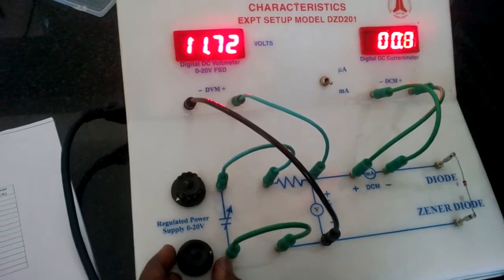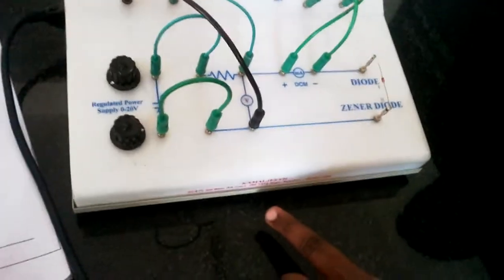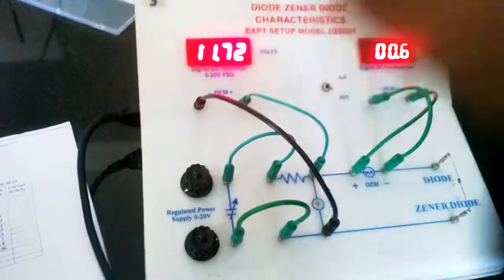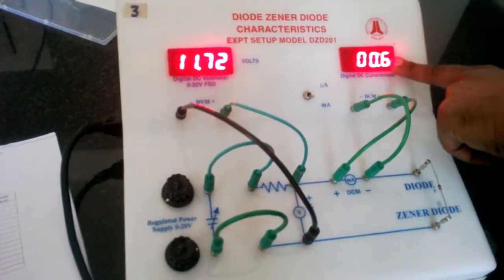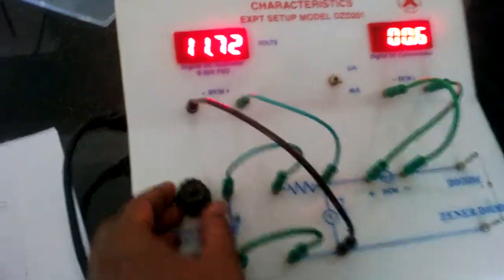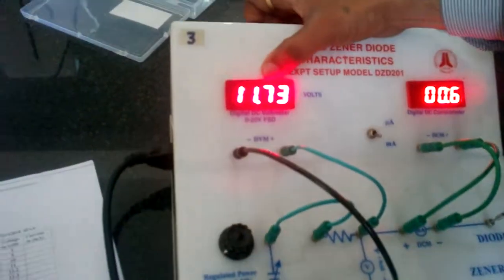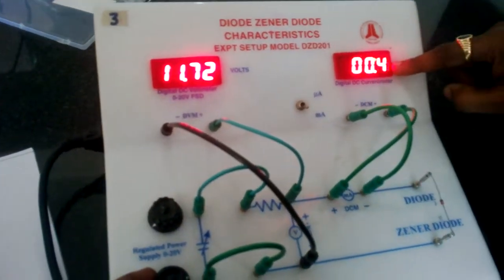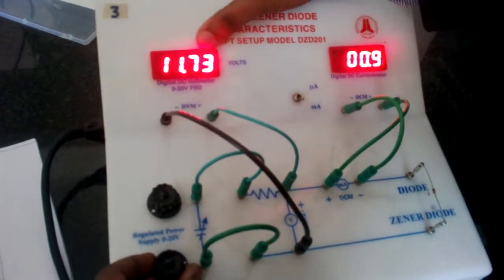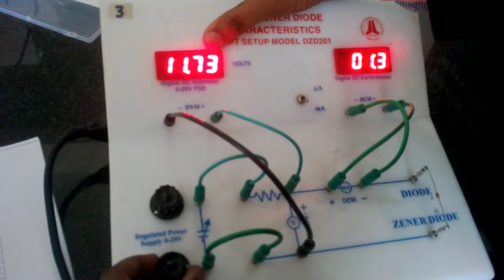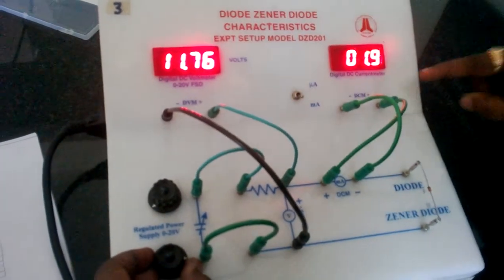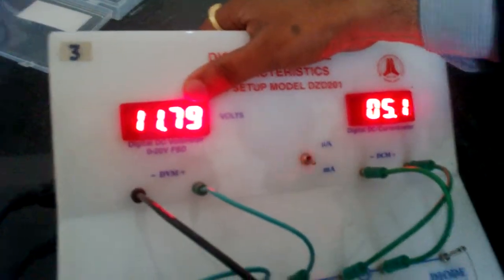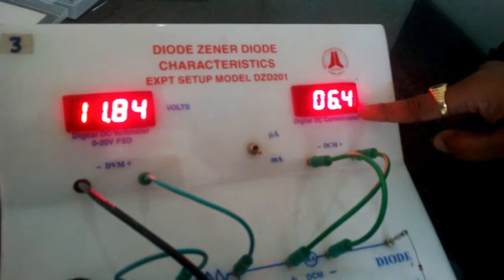You know what the reason is? In reverse bias, it offers more resistance, and once it reaches a certain voltage, the current will increase rapidly, exponentially. So till 11.7 we didn't get any value. For 11.72 we are getting 0.4. We just increase 0.7, increase to 11.74. See, it has reached 1.9. So if you keep on increasing the voltage, there is exponential growth in current,